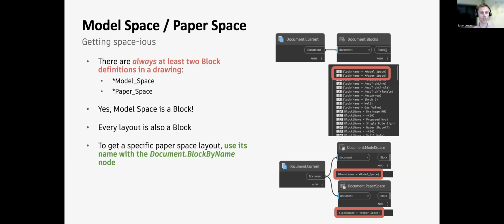So when you're drawing things in model space, you're essentially in the block editor for the model space block. For any other blocks, you're very used to opening up the block editor, editing that block definition, and then closing it out. That's basically what model space is. It's just a permanent block editor for model space. And then every layout tab that you have in AutoCAD is like the block editor for a paper space block for each one of those layouts.